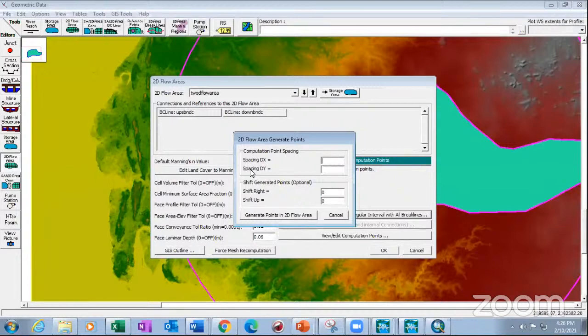For your demonstration, I'm keeping 300 because our simulation will get over within a short time, but accuracy will be compromised for sure. We have to come to the dx and dy values based on the Courant number. Generally it comes around 80 to 120, based on the flow.